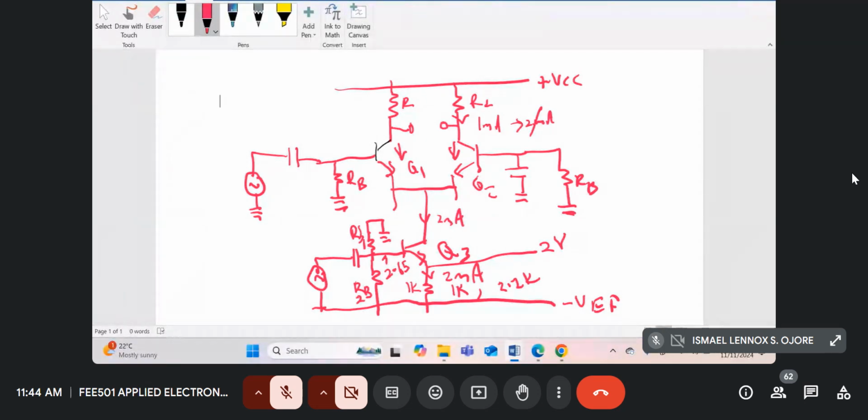Okay, so you have to design it, because this point here is 0 volts, but I like designing from minus VEE if I use that as my reference. So the voltage at the base of Q3 should equal what voltage we're using as the supply voltage, plus 10, minus 10, or in the lab, what voltages are you using?